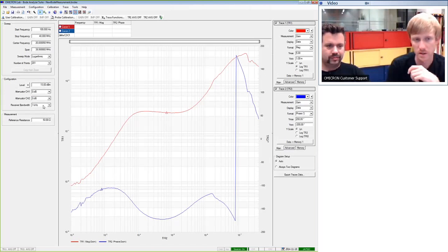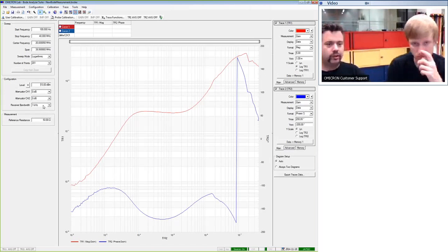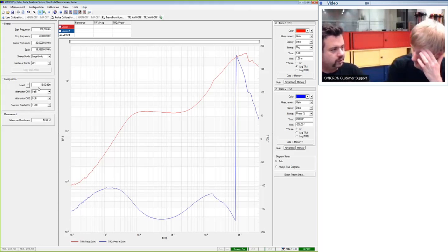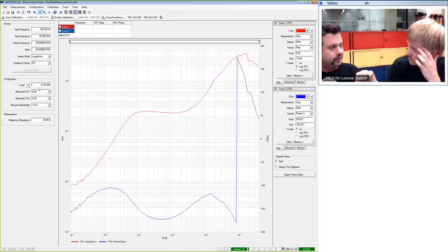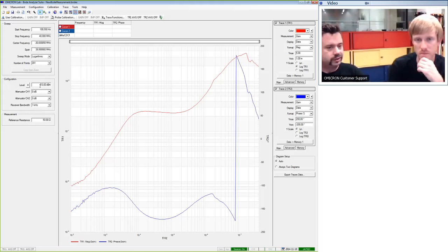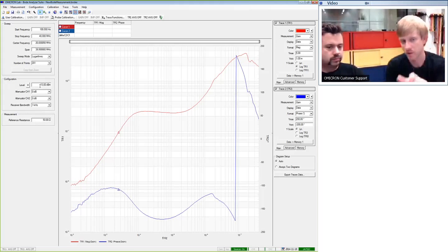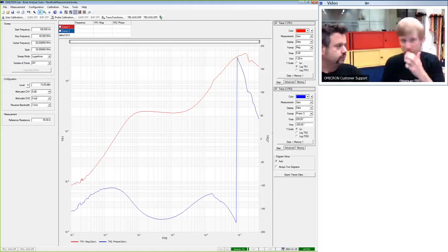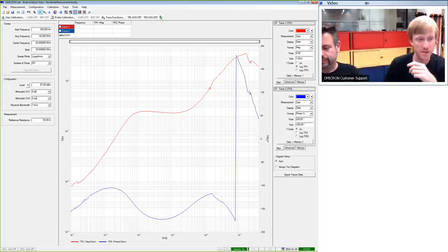And what else? You can also, if you want to slow down the measurement a little bit, reduce the receiver bandwidth. The receiver uses a narrower filter, so it needs a longer time to settle. But the advantage is that the sum of the noise that you measure is less in relation to the useful signal, and therefore your signal-to-noise ratio is improved. Okay, but I think here I will just keep it set to 1 kHz. With the switcher, we will then see that the receiver bandwidth is very important since we have a lot more noise in the switching system.